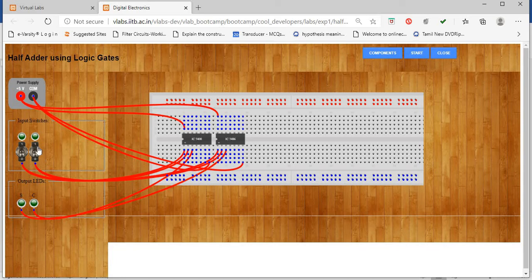And we have two common inputs given to pin numbers 1 and 2 of the AND and XOR gates. The output of the AND gate is nothing but a carry, and the output of the XOR gate is nothing but a sum. So hope you have given the connections rightly. While dragging the wire, if I place it somewhere wrongly, it will notify us.